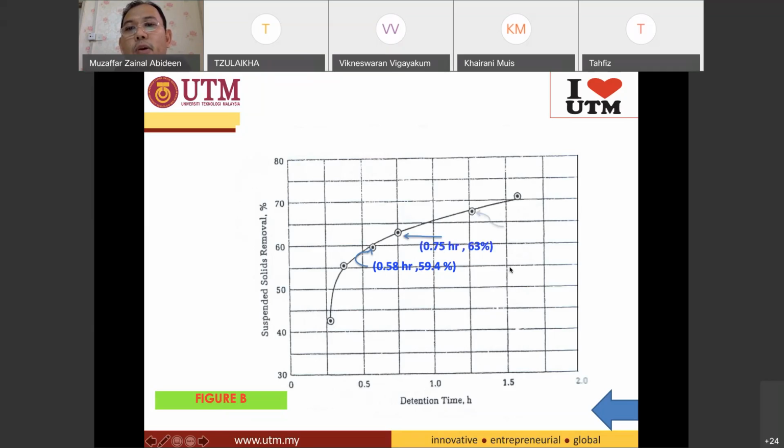And this point is 1.27 hour, which is equivalent to 76 minutes, and that corresponds to 68%. Then you have your 65% there. This is 60, there's 70, so 65% is in the middle. You draw one line there, and we go down to find our H, which is 0.9 hour or equivalent to 54 minutes. I'm sure that you want to take a picture of this. You may do that.